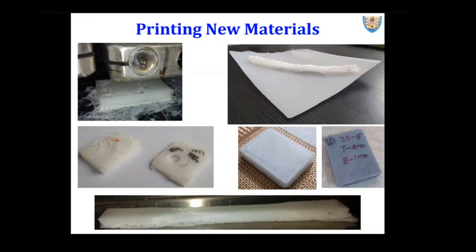I'll just go ahead. So here we have a sample, and then the sample is printed on the base plate. Even it has made the base plate to get warped. And this is a serious issue when you try different crystalline, semi-crystalline materials. Then you have to optimize the printing parameters as I mentioned earlier. And what you see at the bottommost image is the perfectly printed type 1 tensile sample, which we compared with compression molding, which we compared with injection molding.